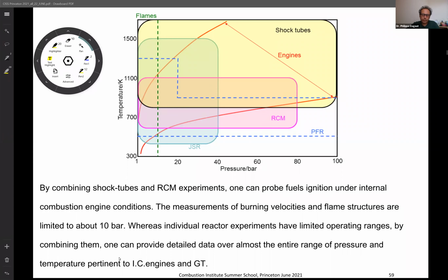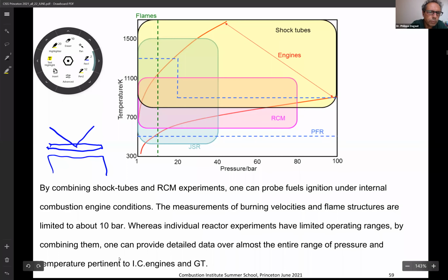If you can imagine that you have a very tiny, flat flame just above the surface of the burner, and you bring in a huge cone for sampling, let me try to draw something. Then you would have this thin flame above the burner, and here you will bring a huge probe. Then, of course, you will cool a region around the probe, and you will also perturb the flow. So this is one configuration which is a bit annoying. I hope I answered your question.